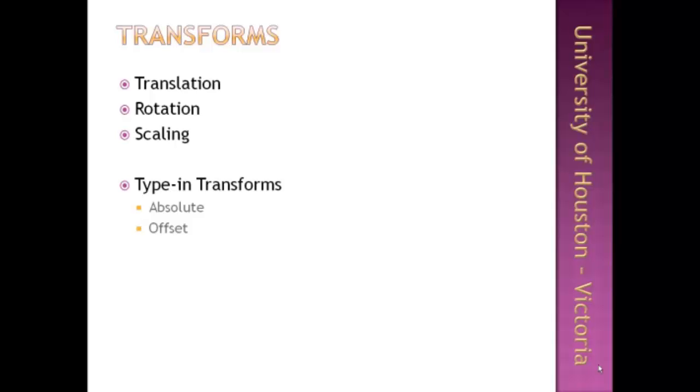So in your main toolbar of 3ds Max, as I showed you last week and earlier today, you have the select and move gizmo, the select and rotate icon, and select and scale. These 3 icons on the main menu bar allow you to apply transformations on your 3-dimensional objects in 3ds Max.